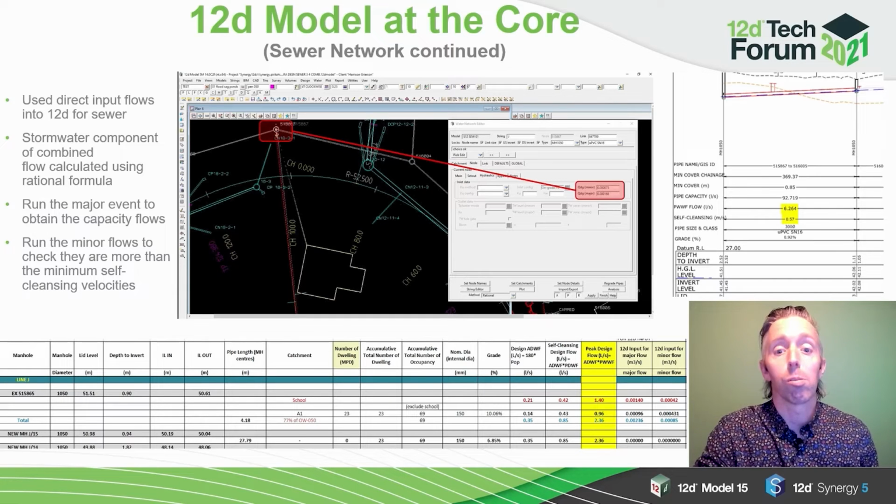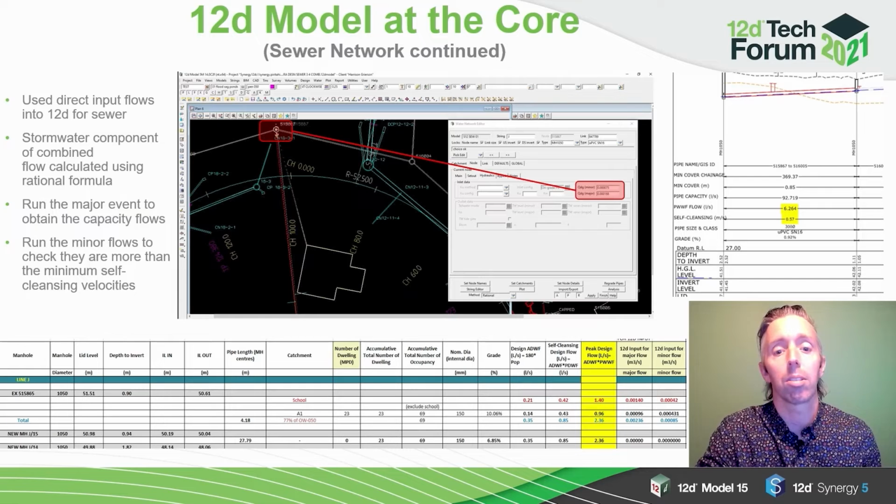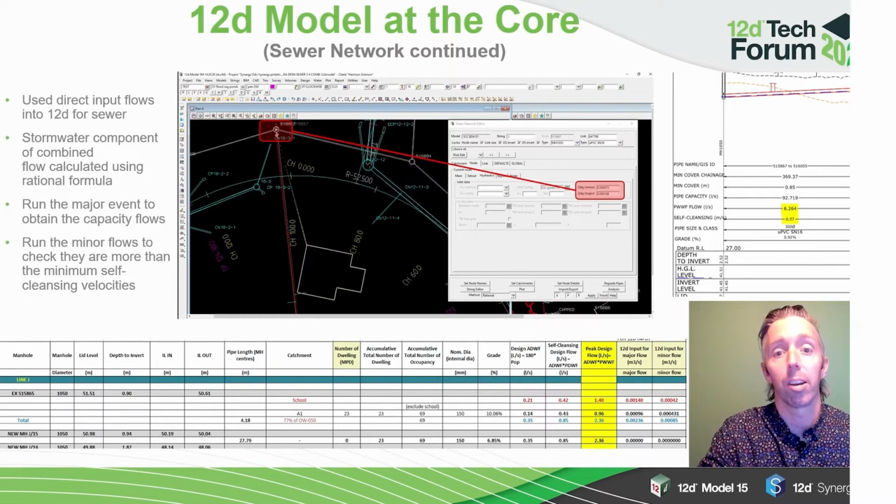We then also ran the stormwater component using the dynamic analysis, where we have all the stormwater catchments drawn up prior and using the IFD table previously shown. This gave us the combined flows, and then we removed the catchments and reran the analysis to gain just the sewer flows. In the next slide, I have one of my team record the key steps in a short video as my team found it a unique scenario.